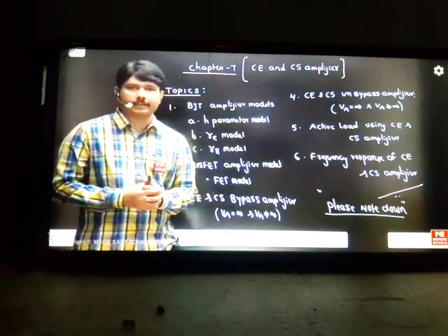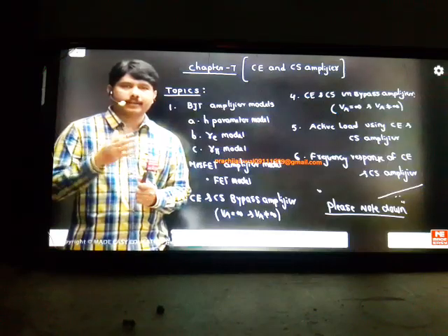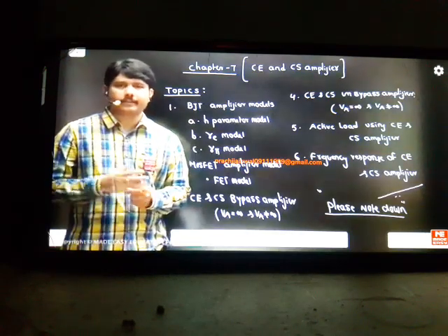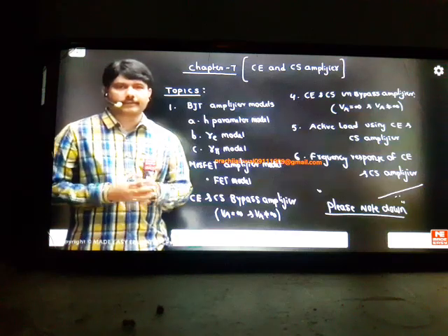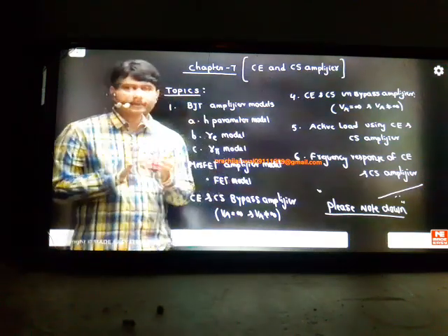Yesterday I think you have seen this in current mirror techniques. VA equal to infinite means theoretical study. VA not equal to infinite means early voltage is not infinite, so we are studying the amplifier practically. So the examiner can ask you questions with infinite or without infinite. That's why we'll try to have 2 different visions. In the same manner, unbypass will also be studied like that. These are the main topics to study.